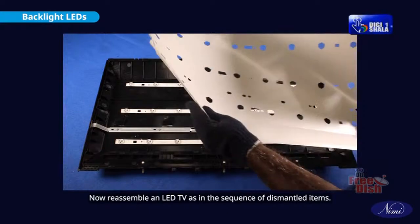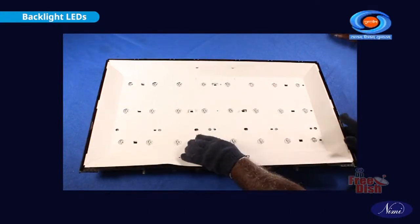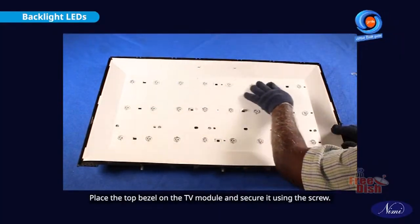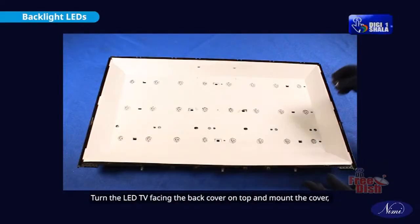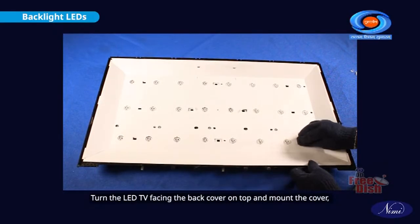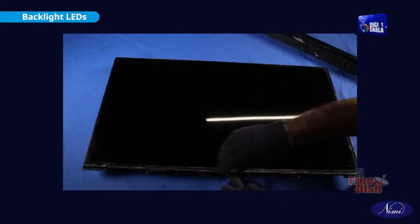Now reassemble the LED TV in the sequence of the dismantled items. Place the top bezel on the TV module and secure it using the screws. Turn the LED TV facing the back cover on top and mount the cover, which was removed earlier, with screws.